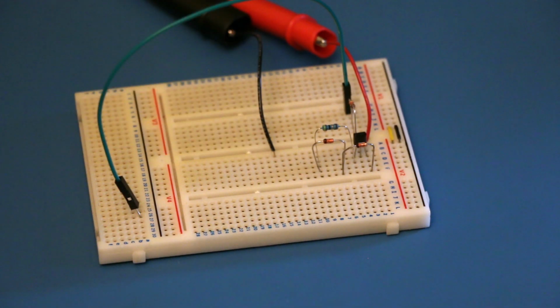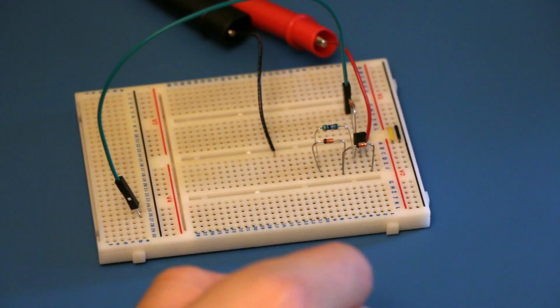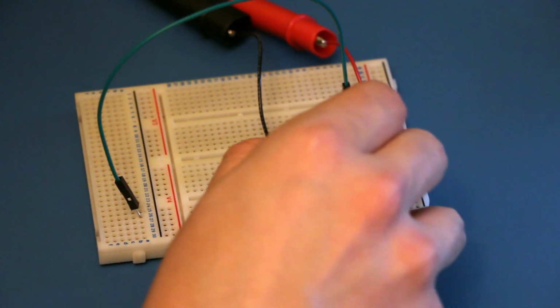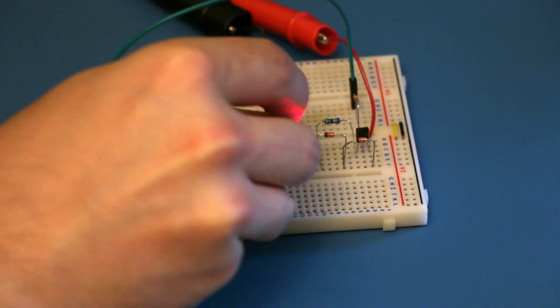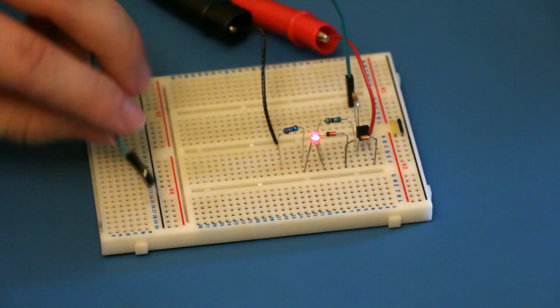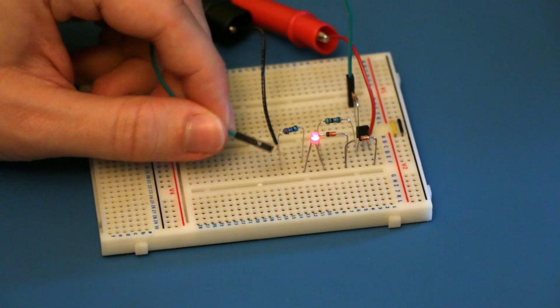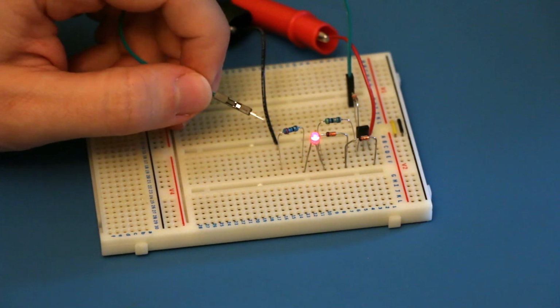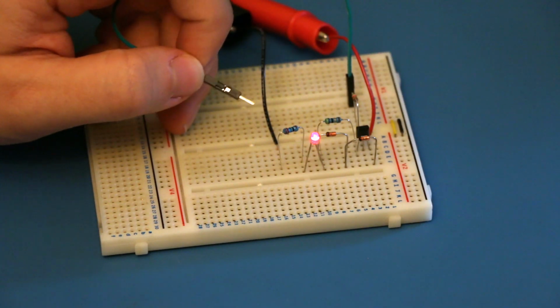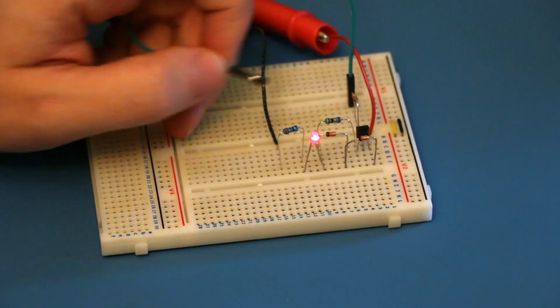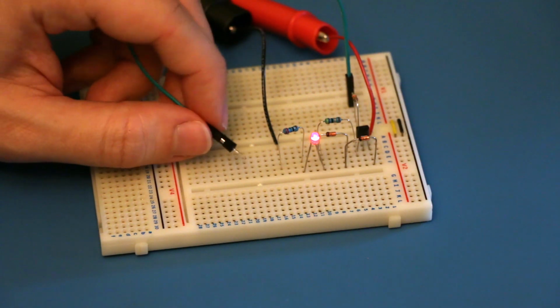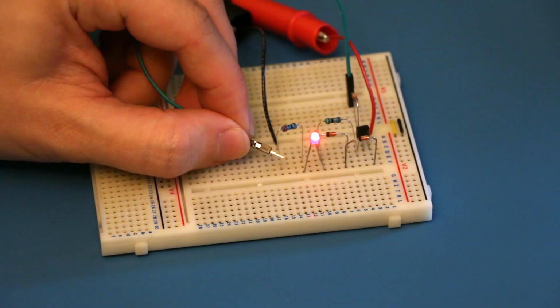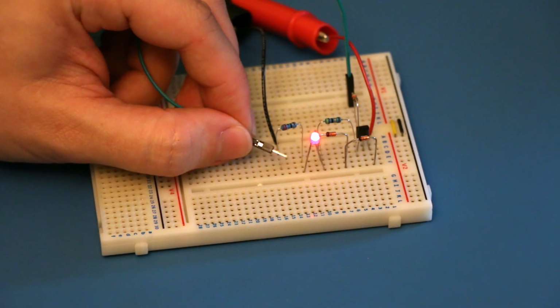To make sure that this works as intended, it's always a good idea to test it. We can make use of a clear red LED, which you may notice from its previous starring role, and a 1 kilo ohm resistor. Now, when I bring this wire to 0 volts, that LED should become brighter because it's being pulled up. Instead of the fixed 1.4 volt drop, it should have a negligible drop across the transistor and then the 47 ohm resistor instead. And sure enough, when you touch, it does get brighter.